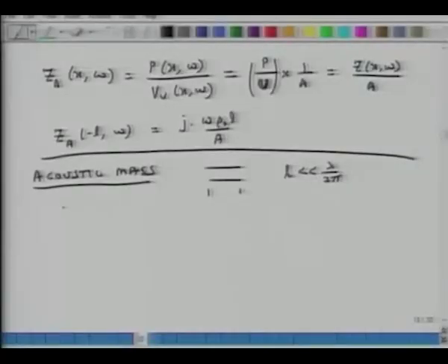If I have a pressure here and the tube is fairly small in length compared to the overall lambda, then because of that vibrating piston, the air will move more or less like a rigid mass back and forth. So if that is the case, then I can use the relation force equals mass times du over dt. This Newton's law is applicable to rigid bodies, that's why I am able to use that. Now force is pressure times area, where area is the cross section of this tube.